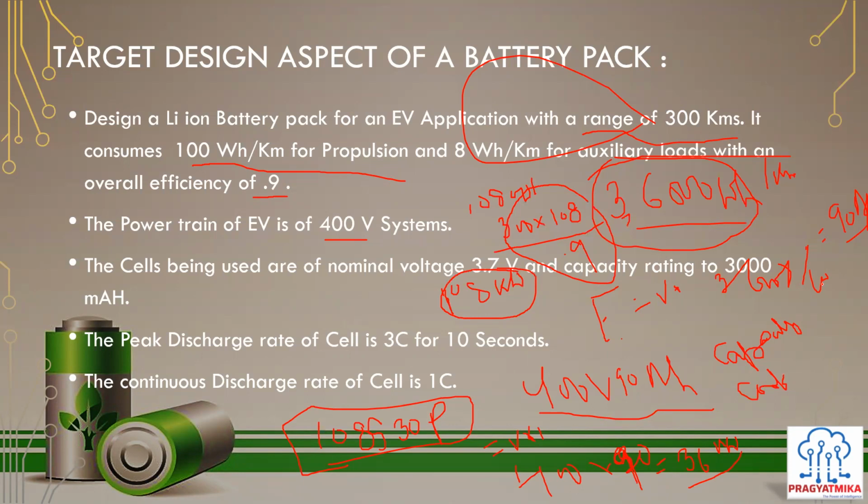This is for four-wheelers, and it is always provided by the powertrain engineer; these are also standard values. Actually, these are estimations we make, but for each country there is a standard drive cycle method. The drive cycle method tells you, for a vehicle of a given rating, how much power the motor or powertrain should take in a given terrain. If it is a flat terrain, this is the amount of power it should take for 1 kilometer. If you are traveling in a hilly region, the powertrain will take more. That is all considered under the drive cycle.